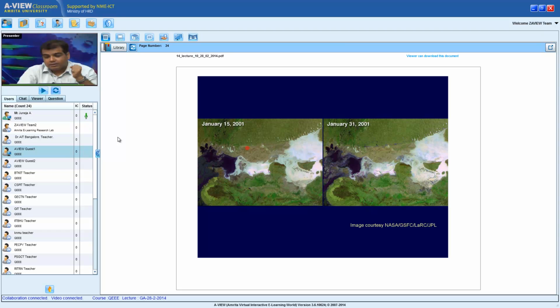This is a salt pan area, because there's a lot of salt. So when more water comes up, you'll find greater white patches on the right hand side. So the upward flow caused by the earthquake loading caused soil liquefaction and then a decrease in effective stress in quite a number of parts in this state. Okay, so as a home assignment, please compare the 2 images and see what your thoughts are on it.